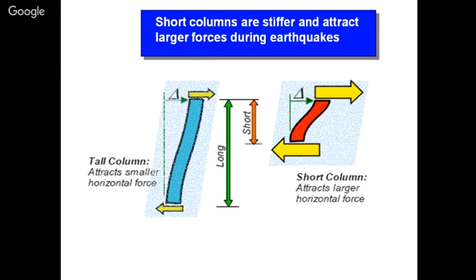Short columns are stiffer. That is the reason they attract more earthquake forces and they are more vulnerable towards earthquake. So if you are having a short column in your structure, you are supposed to give extra consideration to that short column for design and analysis.